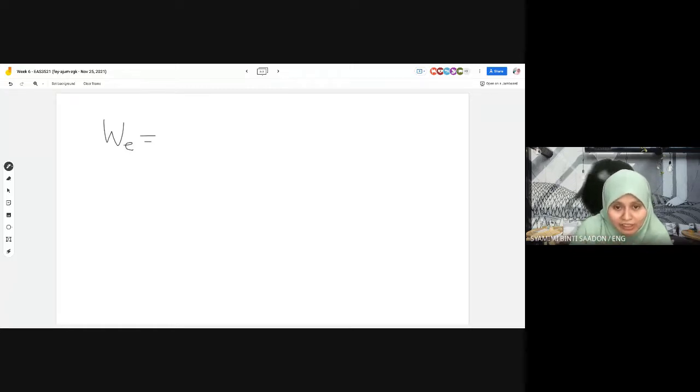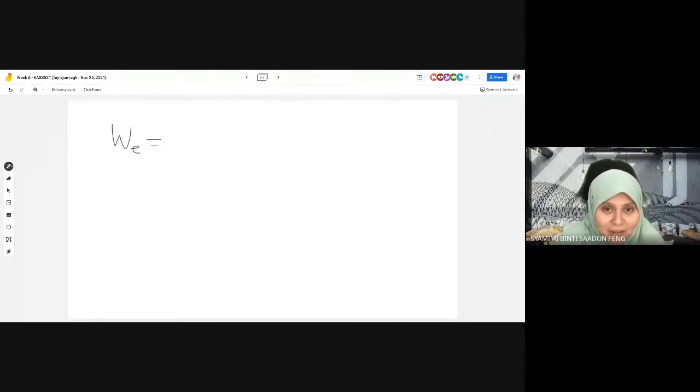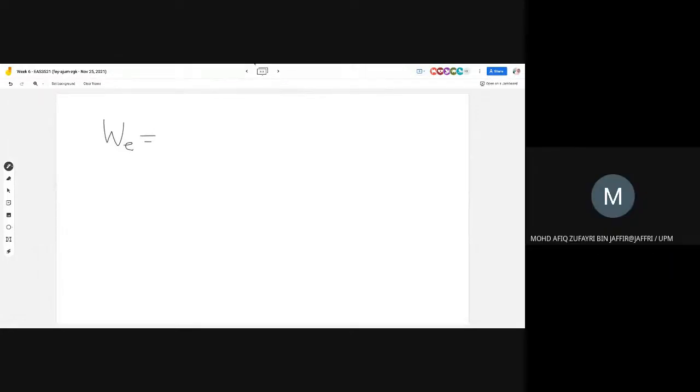Look at the table at pressure 0.3 megapascal because 300 kilopascal equal to 0.3 megapascal. And search for the value of enthalpy that you have calculated, the nearest possible value, and look at the temperature. Temperature tu berapa? So that is your T2 temperature. Okay. Dapat. Okay. Thank you, Doctor.